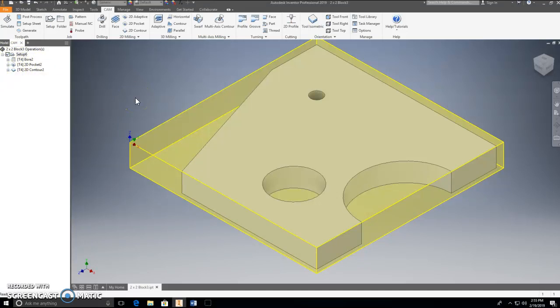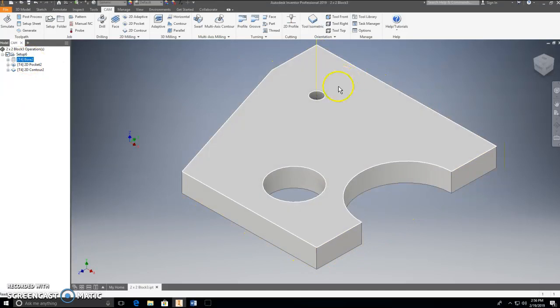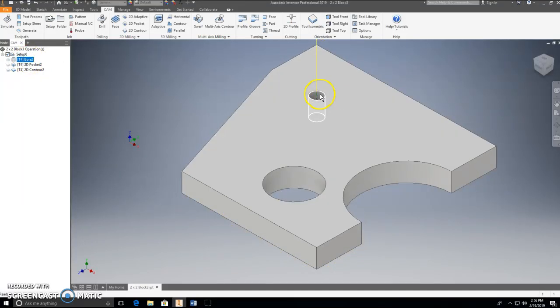So that regenerated it. Now, however, if you got the piece of material that's over 0.125 thick, or one of the 2 pieces of material that's over 0.125 thick, you have one more step to do. Your one more step is you need to change to where you're going to take multiple passes. So, the way that that's going to happen is this. First, for your pocket and your bore, you do not need to change the depth of those, the way that those work. So, your bore is just going to go down.